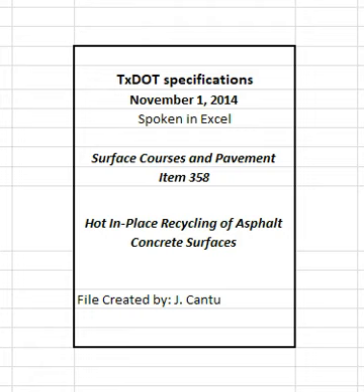The department will provide on the plans all typical sections and any grade change requirements, the depth and width of recycling required, core information from the existing roadway to include pavement layers, lift thicknesses, the asphalt content and penetration value of the existing asphalt to be recycled, and any other data collected from the pavement evaluation.